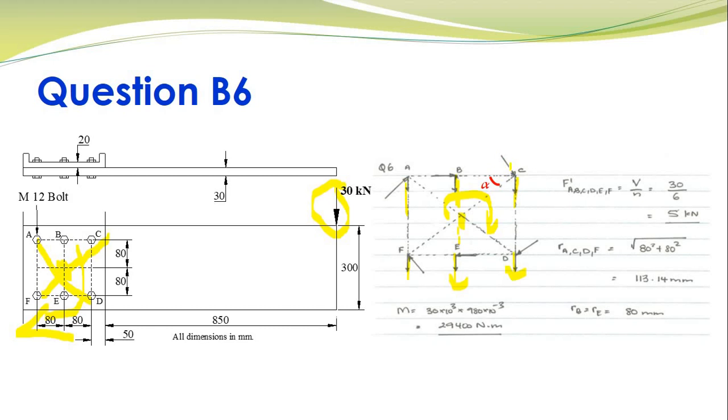In this case this is your lever arm from, let's say, O to I. So this secondary force has to be 90 degrees to this lever arm, and we need to ensure that the moment is clockwise as well. So you'll see that this arrow is in this direction, so this causes a clockwise moment. Now looking at B, this is your lever arm, which is just a vertical line joining O to B and O to E.